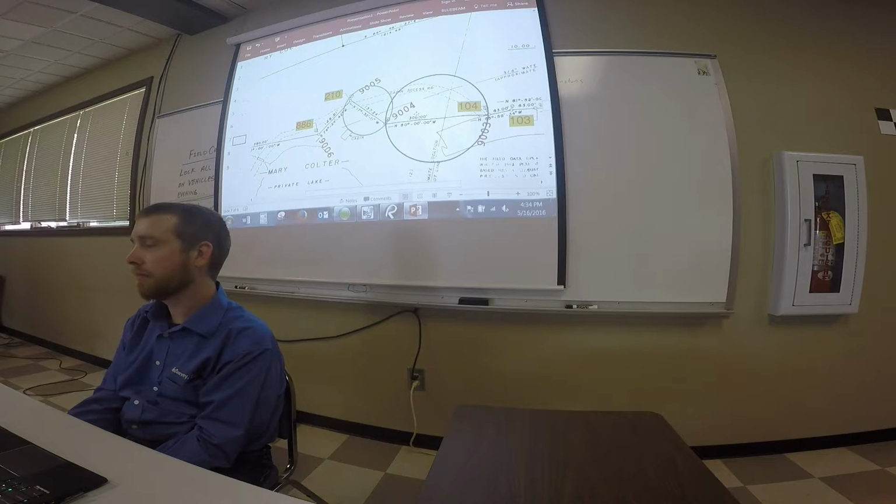Our angular measurement was dependent on a vernier scribed on 2 circles of metal. Okay, but we can measure a distance with a 100-foot steel tape pretty doggone tight, right? So it ended up becoming law that distance is control over bearings, and it still to this day prevails as the preferred method for establishing a corner. So out of all the methods so far, you're going to see that the distance intersection, if it's off of 2 good found monuments, is going to be the preferred method to put that pin in. You know, in the words of the late Trim Baker, though, we're not building a piano here.